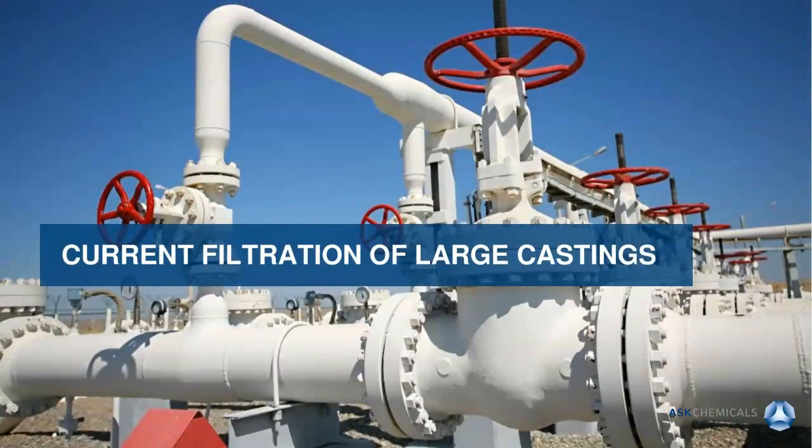The filtration practice on large castings, and here I really mean between 2 and 35 tons at least, is different compared with filtration of small ones. Unfortunately, it is usually not possible to reduce the number of filters to ideally match the number of ingates determined by the technicians as optimal for the casting.